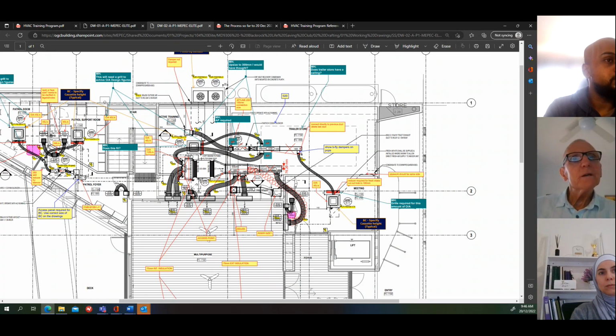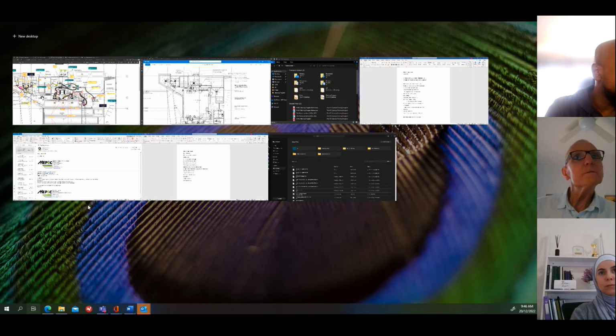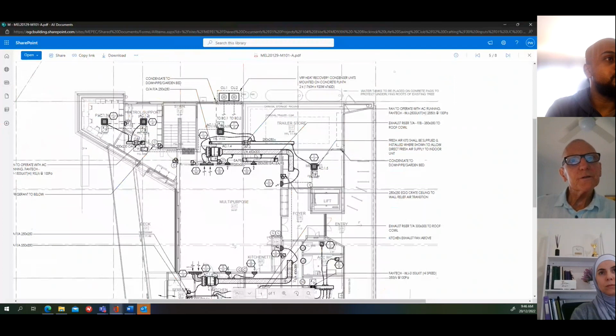let's have a look at that again. So that size on the design drawing, 450 by 300, is actually the airway size, right? Yeah. And if that's internally insulated, you've still got to maintain the 450 by 300 airway size and add the insulation.